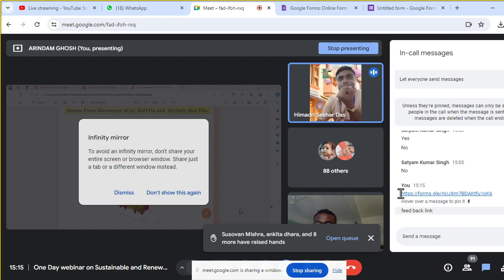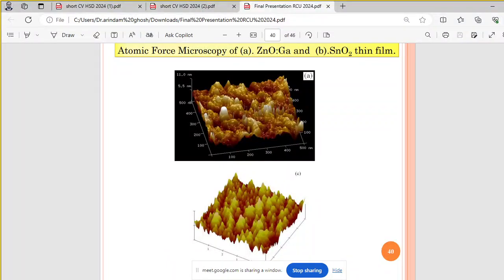The 3D topography of this gallium doped zinc oxide anode surface shows low surface roughness. So the gallium doped zinc oxide anode based OLED shows a longer lifetime compared to the commercial fluorine doped tin oxide anode based OLED. Next, we also performed some characterizations such as luminescence, current density, and external quantum efficiency of this device, and compared the commercial sample and our sample, shown in the next slide.